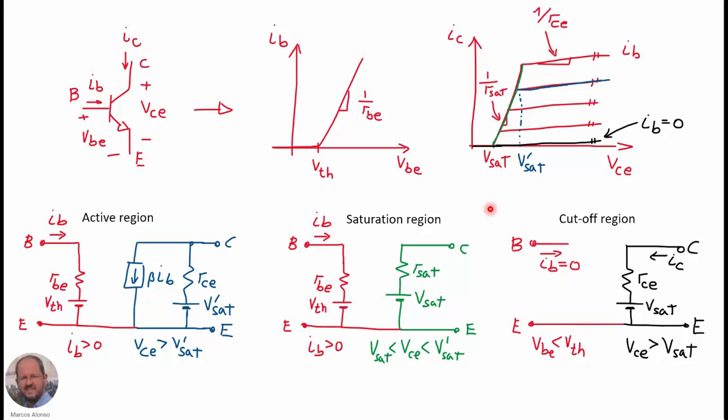So the idea is that usually when we teach this type of circuits using BJT transistors, we model the transistors with these simple piecewise linear models, and then using the built-in models that we have for the BJT transistor in LTspice, it's not possible to get the same values that we get when studying the circuits with a piecewise linear model. So I think that this is very interesting also for the students to have this type of models, so they can study the circuits and then do the simulation to check if the analysis is correct.